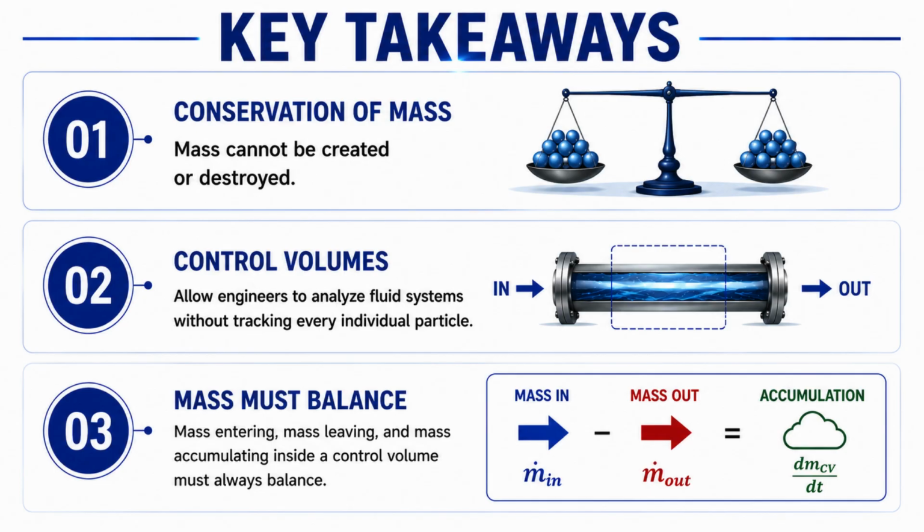Let's summarize what we've learned. Conservation of mass tells us that mass cannot be created or destroyed. Control volumes allow engineers to analyze fluid systems without tracking every individual particle. Mass entering, mass leaving, and mass accumulating inside a control volume must always balance. And by understanding this simple principle, engineers can analyze everything from household plumbing to aircraft, power plants, and rocket engines.